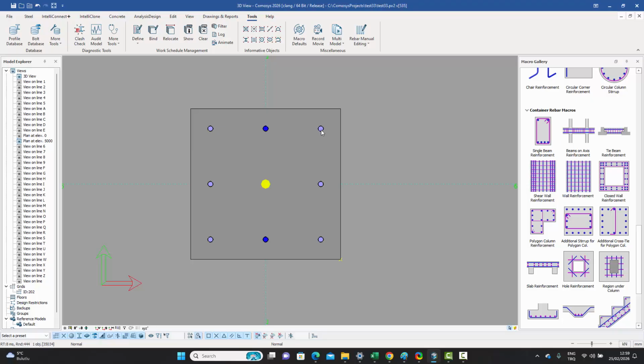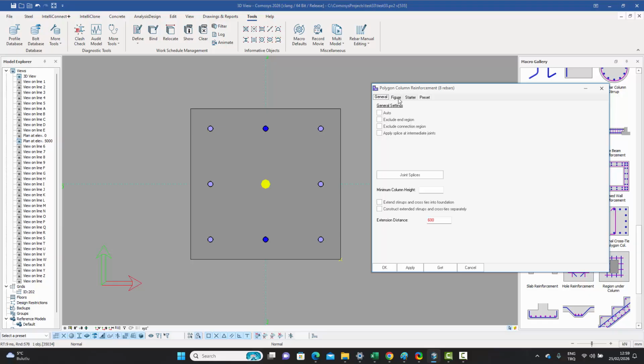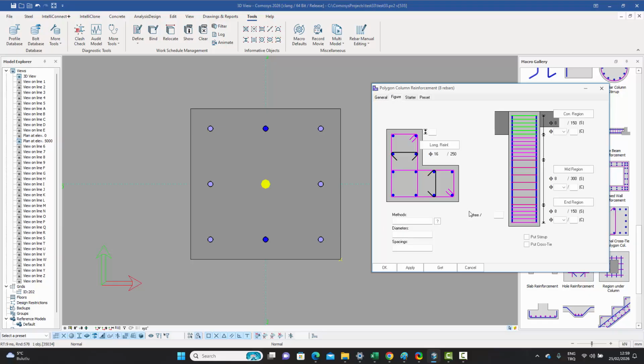It means that the number over there, let's press M twice. So you can go back into the macro by selecting any rebar and pressing M twice. I'll explain that because normally it will leave surface macros. So if you press M once, you will access this surface macro. But if you press M twice, you will access the original column reinforcement macro. And then if you press enter, the column macro dialog box will open.